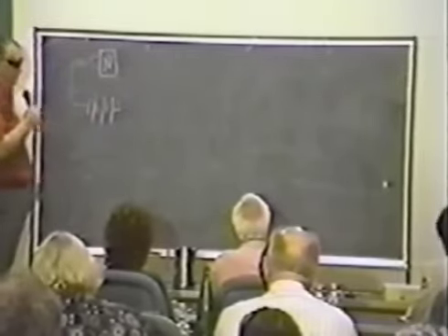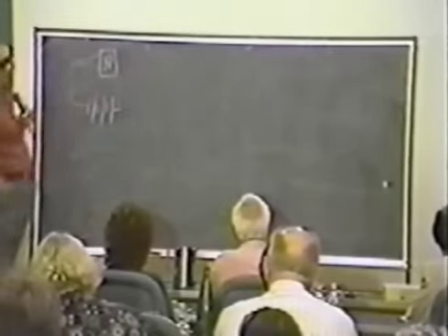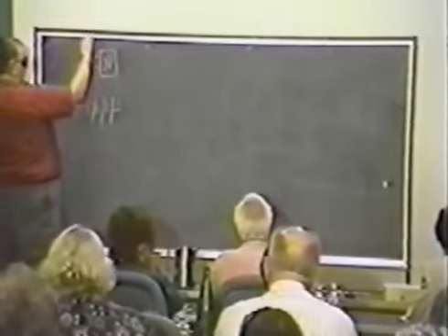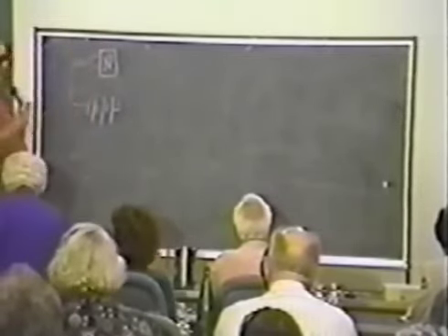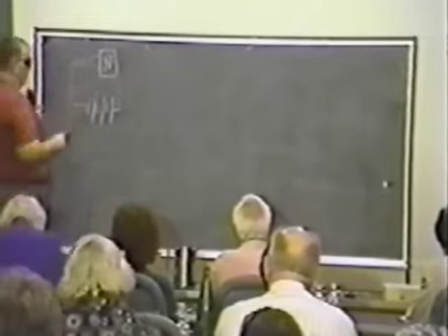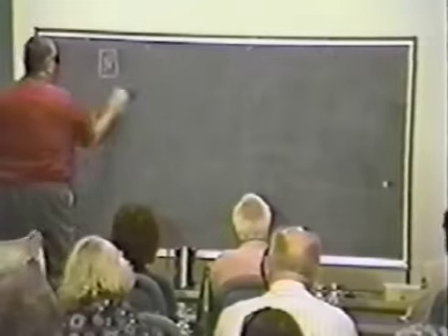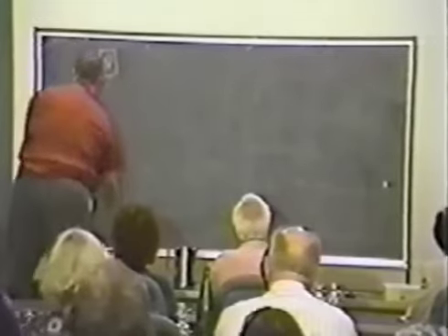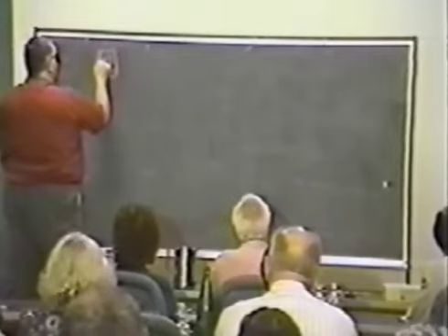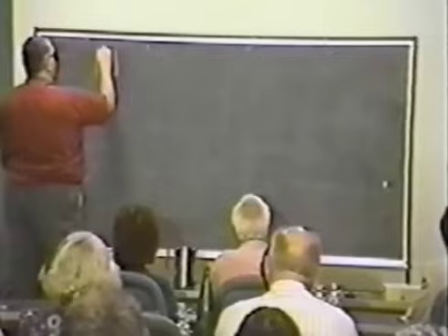And you electrochemically etch, you use a chemical which is a salt of the semiconductor, and you etch an absolutely flat face that is molecularly flat on the surface of the germanium crystal. Then you shut that off. Then you put on top of that a metallic contact.